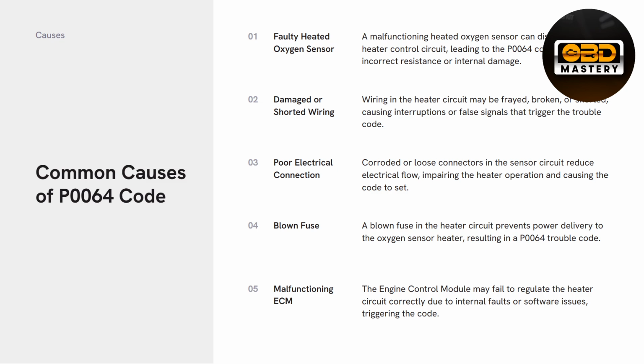So let's go ahead and move on to the causes. Like I said, you can read on the right what exactly happens. However, the causes could be a faulty heated oxygen sensor. Number two, damaged or shorted wiring. Number three, poor electrical connection. Number four, blown fuses. Or number five, a malfunctioning ECM.